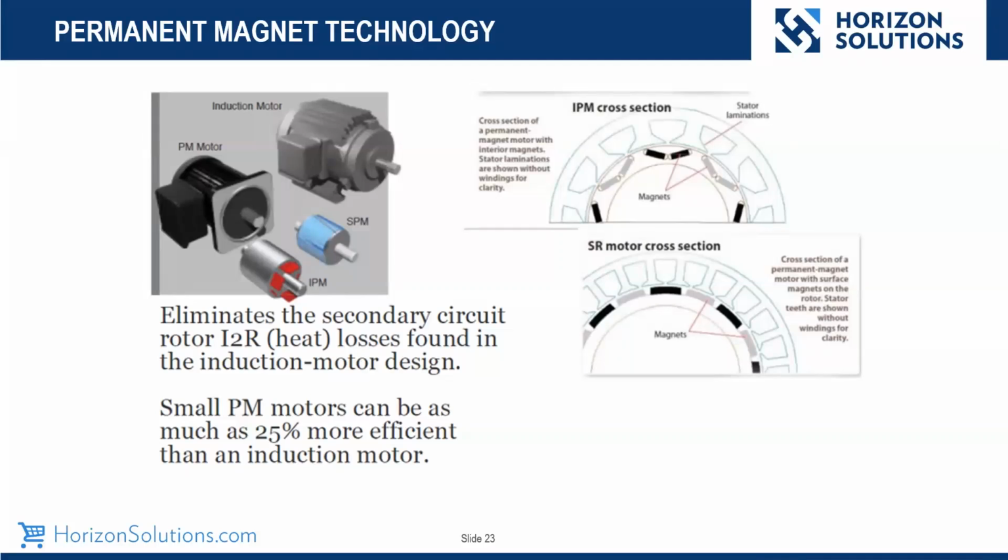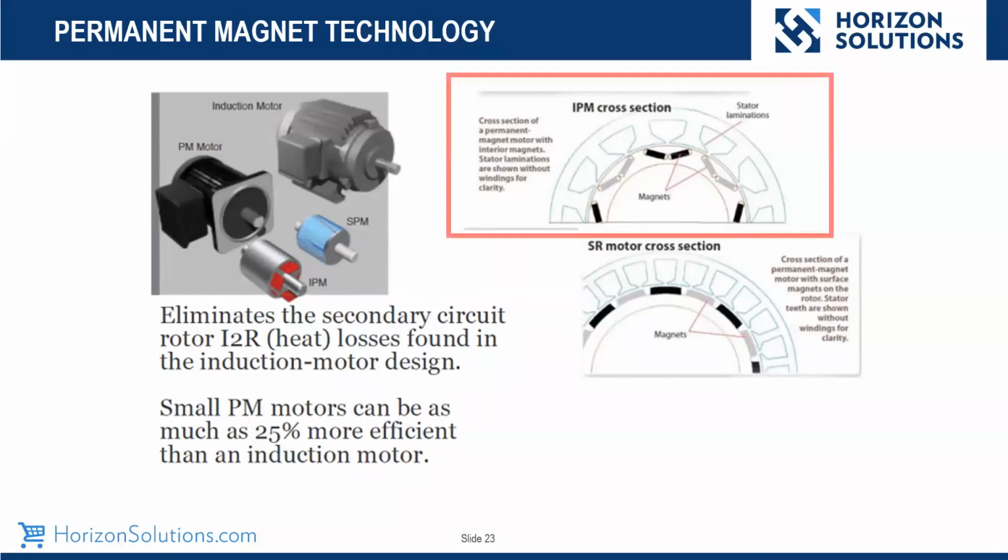Let's move on to different types of motors for this technology. We have the induction motor, which people are probably very familiar with, maybe not, and I'm really pleased if you're here and you don't know much about induction motors. You're probably learning quite a bit. But we also have other motors that we drive with VFDs. A lot of our customers don't realize this, but you can definitely reduce your losses using permanent magnet motors or switch reluctance motors. Both are actually able to be tunable with our VFDs.